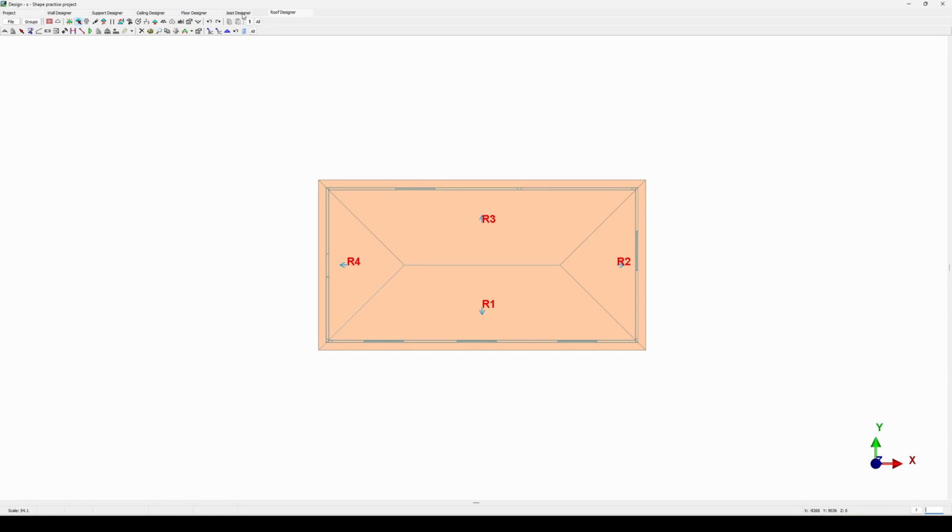With that said, we'll insert our first set of hip trusses by going to our bottom chord, top chord tools right there. As we've mentioned during the gable tutorial, we'll use the top chord to make sure that we select the correct roof planes that will be shaping our hip roof. In this case, we need to make sure that we select the hip side first, so that triangular bit, then the two sides right there.